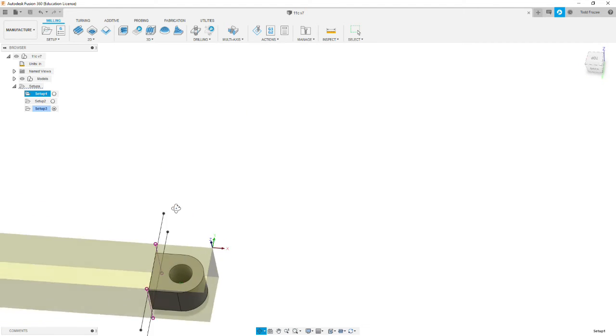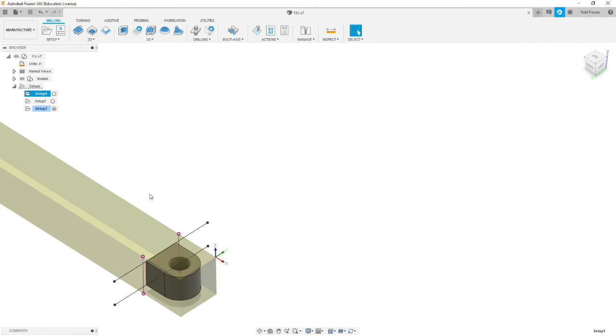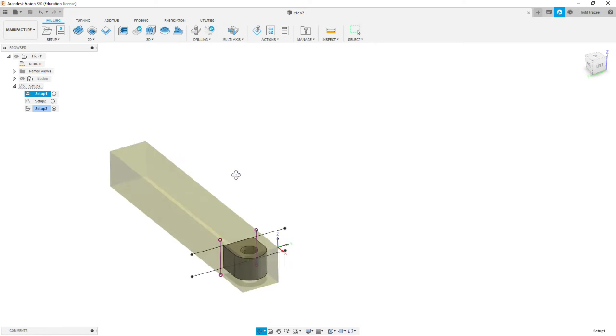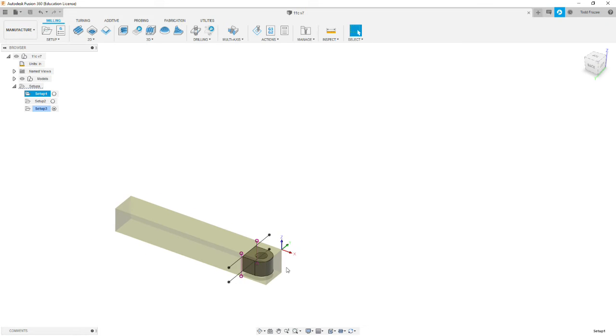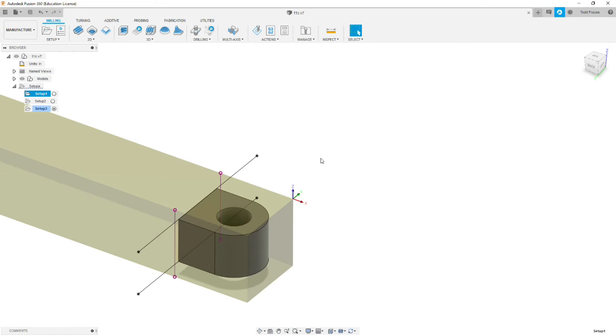You're going to rotate the part so that we're looking at it similar to the operator's position, with X going right to left, Y away from you, and Z facing up. Now this first operation, we're really just doing one routine, and it's to machine down to the face I have highlighted. We're going to use a 1/2 inch end mill to relieve that material, and we need to cut past this line so that when our 1/8 inch end mill cuts on the opposite side of the line to part off, it doesn't have to cut through the material that was left by the 1/2 inch.